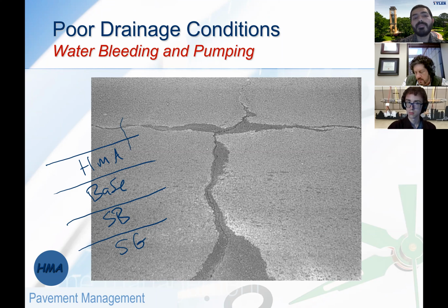So once water penetrates all the way to the base and sub base, those are crushed aggregates, just good aggregates crushed really well, and that's about it. And when aggregate is crushed, you're going to end up with all kinds of sizes. You're going to have, again, up to three-fourths of an inch or even an inch worth of a big gravel piece, but it can be all the way down to very fine materials.